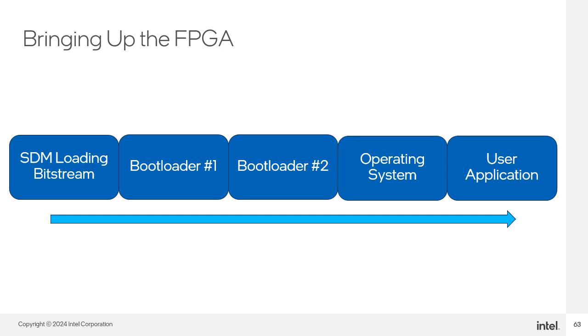U-Boot secondary program loader, which Intel provides the source code for on GitHub, and the ARM trusted firmware, which is also available on GitHub. The second stage bootloader is the second boot stage for the HPS. The first stage bootloader initiates the copy of the second stage bootloader to the HPS SDRAM. The second stage bootloader typically enables more advanced peripherals, such as Ethernet, and supports a command line interface.